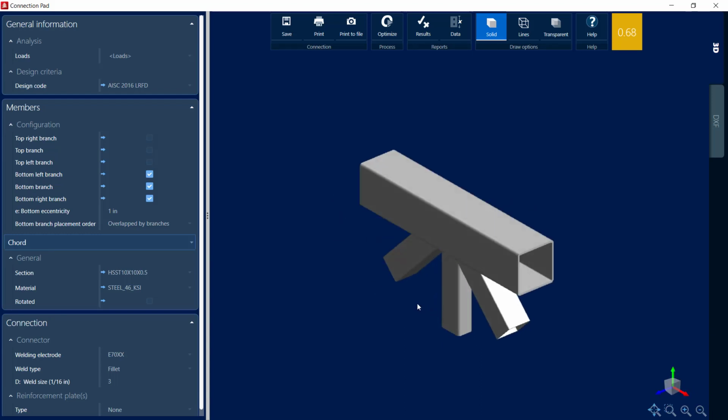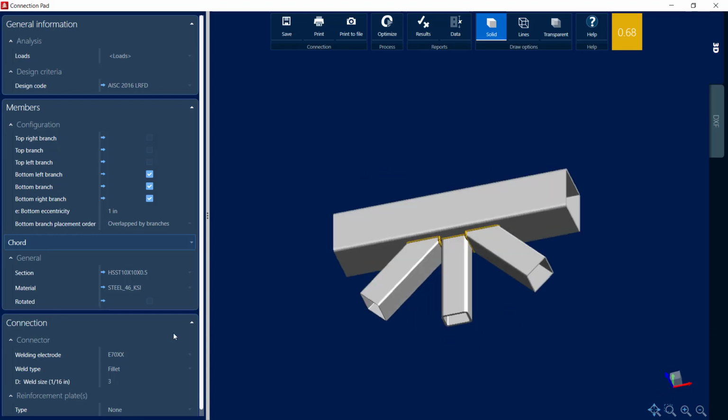So here is my tubular truss connection. This would be a fully welded connection. Now I do like to remind you, for a tubular truss connection, since I selected the AISC 360-16, we're going to use Chapter K. That would be additional requirements for HSS and box section connections, and it uses this along with the AISC Steel Design Guide 24. That's the design guide for hollow structural section connections. Okay. Now here again, I can see my color coding and my interaction ratio, and it's in yellow, which does mean that I received a warning.